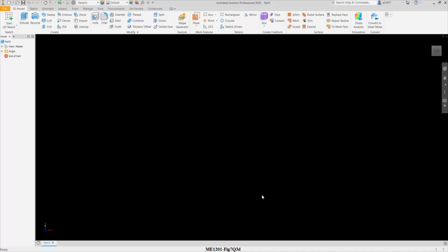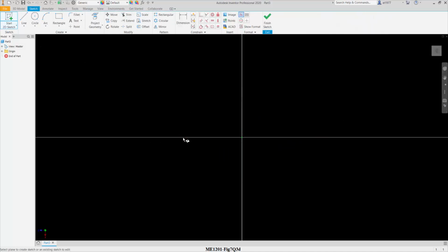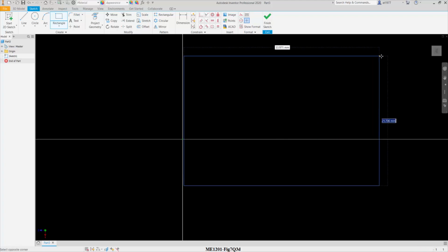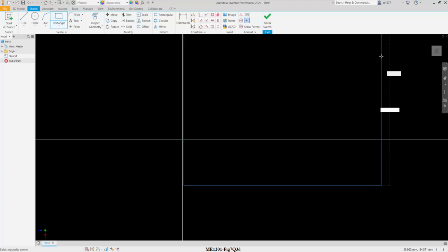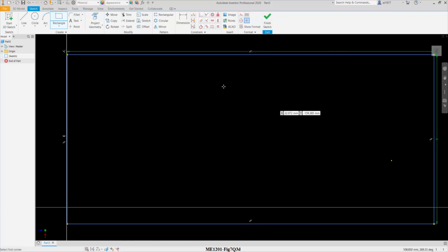In this video, I will show you how to create Figure 7 Question 3D. Start off with a 2D sketch. I'll select the XZ plane to create the plan view. Rectangle, 80 by 180. Okay. After that, I'll constrain center the midpoint of the line to the origin.